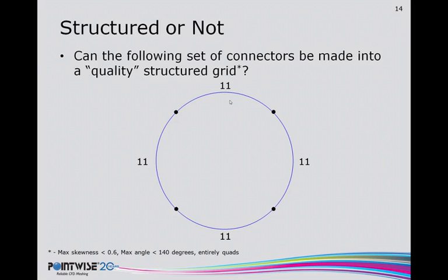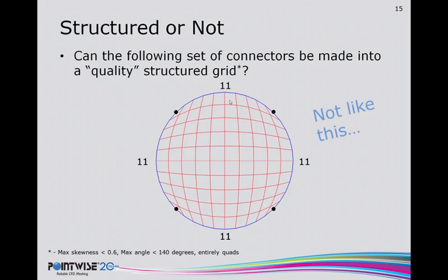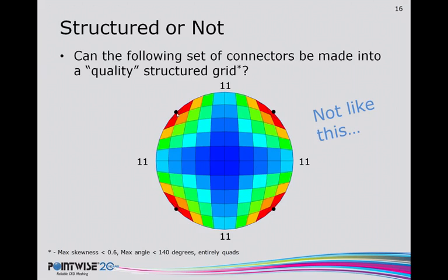So take, for instance, this circle. So we have a nice uniform spacing around the edge. We could theoretically generate a structured grid in this domain because the opposing edges are balanced, but the geometry has imposed a very hard constraint here in that this maximum included angle is going to be very, very large and is dictated by the boundary. And that's simply because we're putting one corner of a cell here and then splaying that cell outward so that the adjacent edges match up.